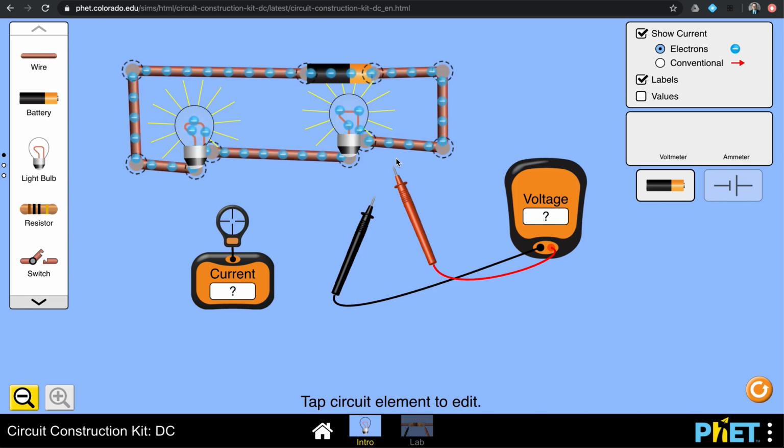You're going to actually build some circuits, some in series, some in parallel. And you're going to measure the currents and the voltage values. The big idea, a series circuit has one path only. Every single electron coming out goes through every load in the circuit. What I had before, they had different paths. It didn't have to go through each load, and we call those parallel circuits.